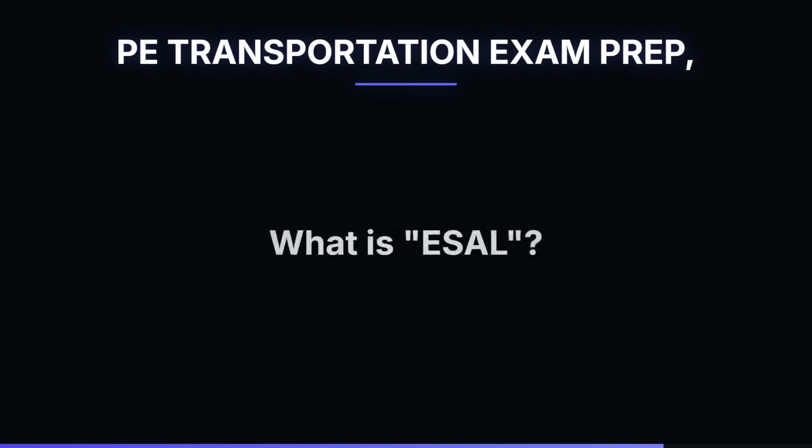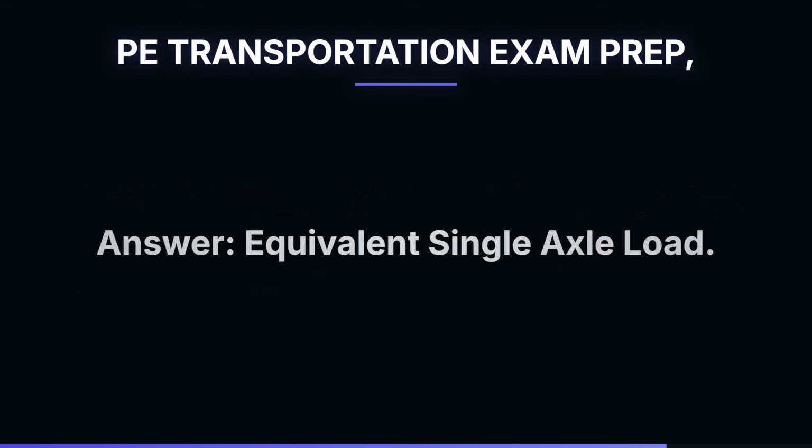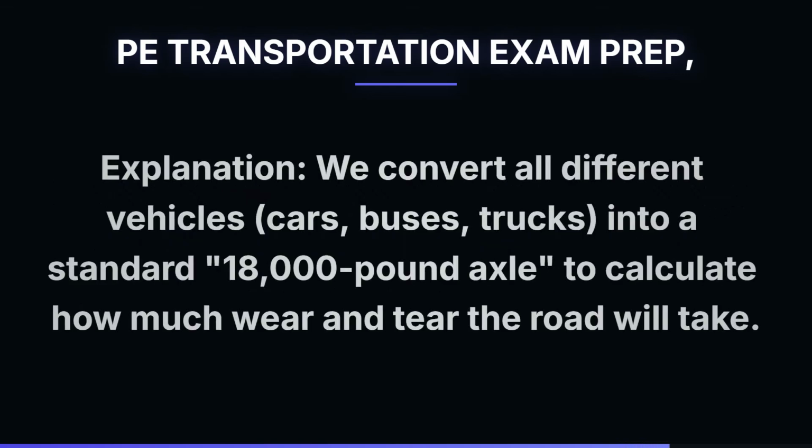4. What is ESAL? Answer: equivalent single axle load. Explanation: we convert all different vehicles, cars, buses, trucks, into a standard 18,000-pound axle to calculate how much wear and tear the road will take.